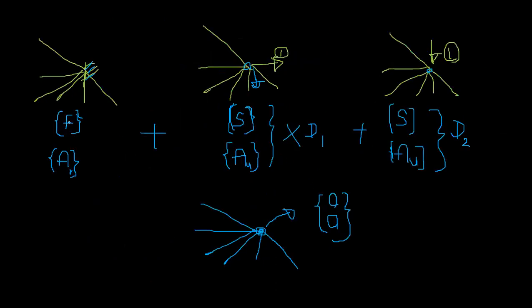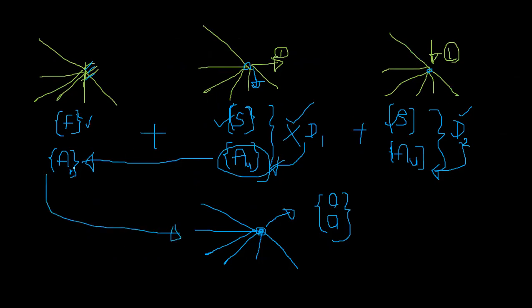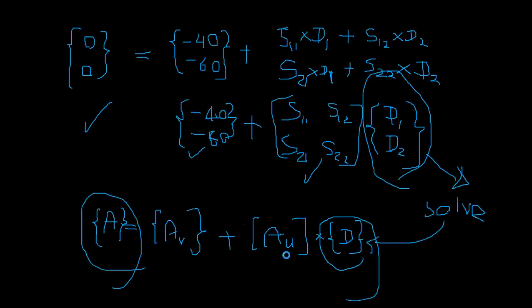You get the equilibrium using forces and multiply it by the original displacement, and you then find the displacement, and then you multiply the action units from that displacement and calculate the actions back on the original figure. This is zero. So once you add these, you get the correct final member forces. Our actions were the member forces, right?